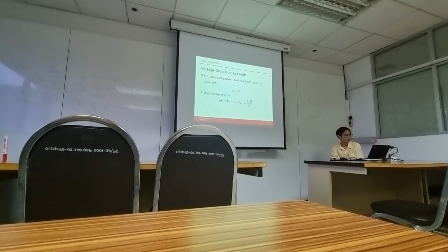Next, we have the constant power load. This time the load power is constant. So it means if you say, okay, this is the nominal voltage, this is P and this is Q, the power P and also Q is constant, and does not depend on the voltage.